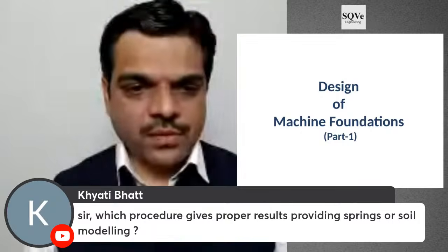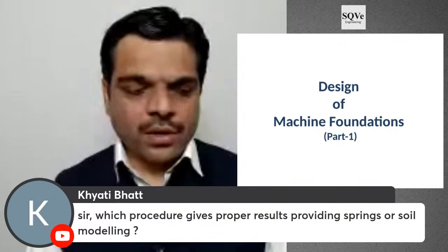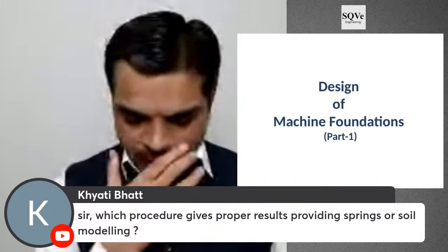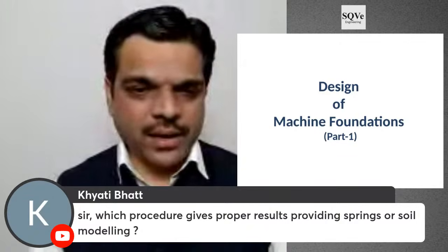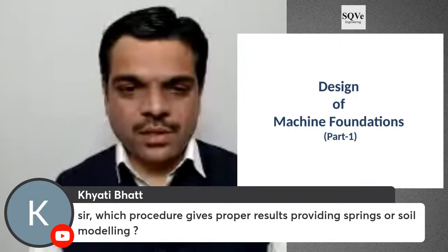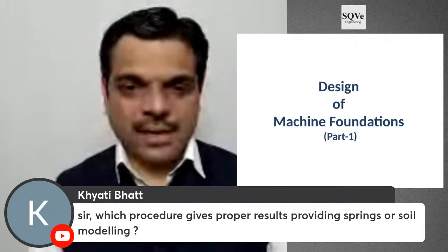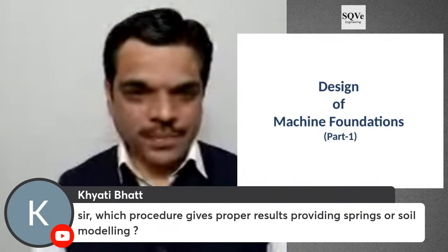Khyati is asking, sir, which procedure gives proper results, providing springs or soil modeling? According to me, whatever software we have, it would give the appropriate result with springs. Modeling of the soil, at least I have not tried in any project. We were only modeling it with springs.